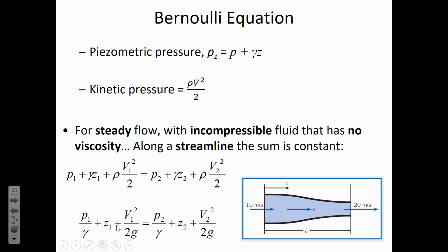In the direction of flow. What this formula allows you to do is, if you know the pressure at 1 and you know how the velocity is changing, then you can predict the pressure at 2. In this specific case, you'll notice that the velocity is going up. If the velocity is increasing, and we're considering 2 points at the same horizontal elevation, so Z1 and Z2 are equal, then how would the pressure be affected by the fact that the velocity is going up? If V is going up, what happens to P?